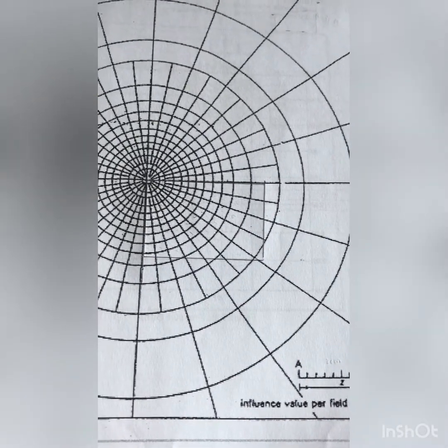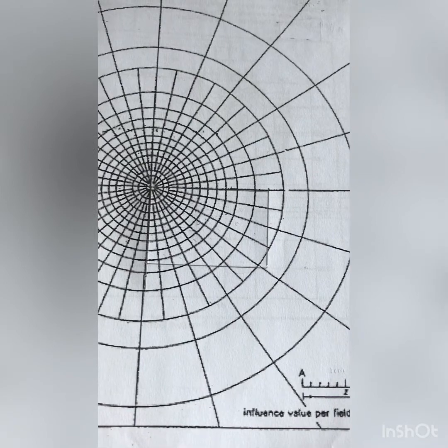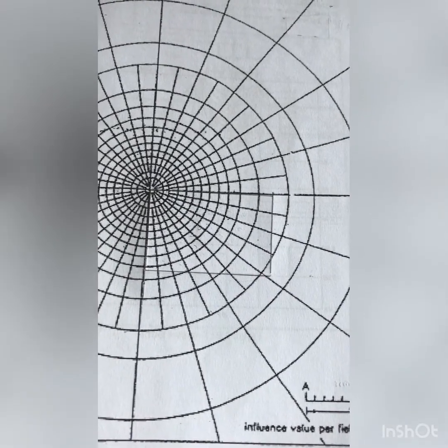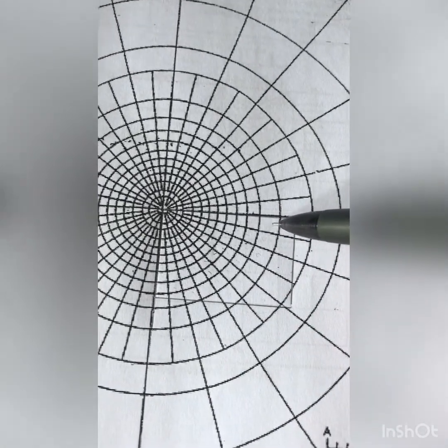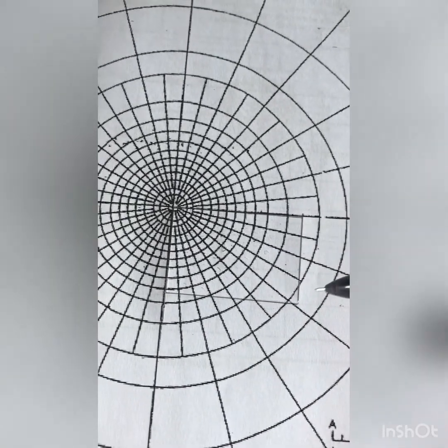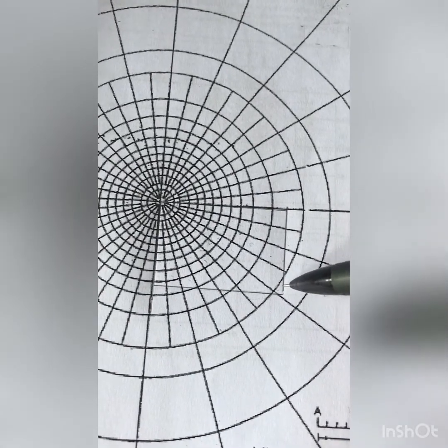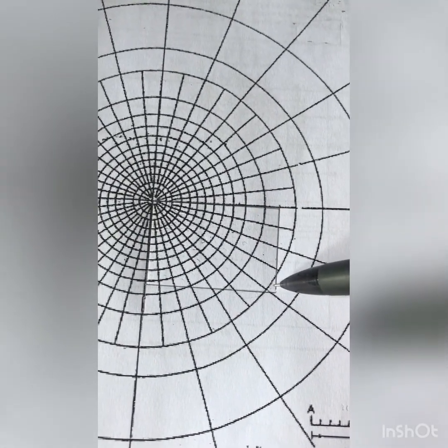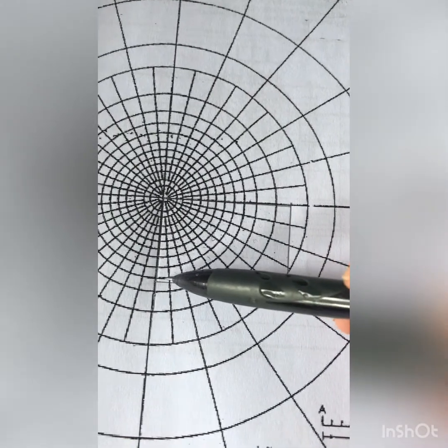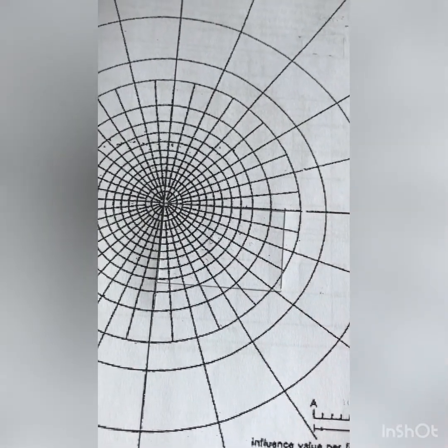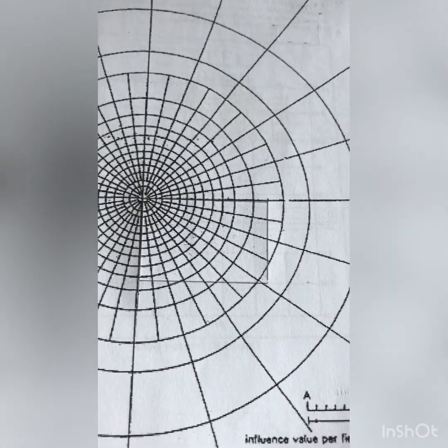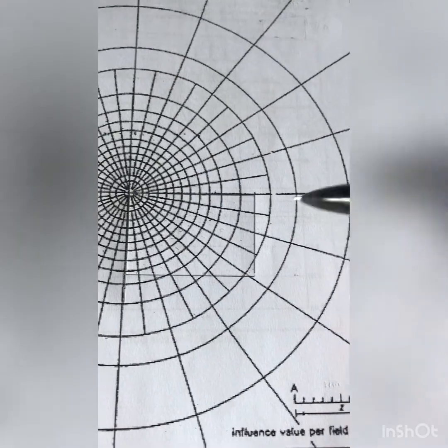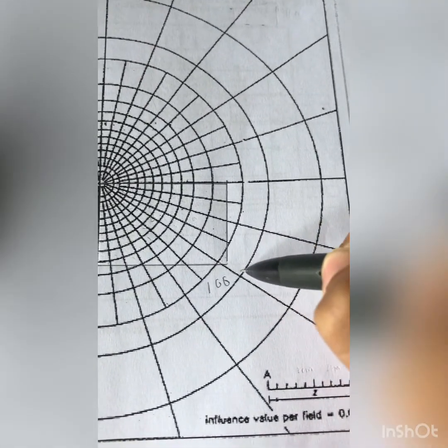So back to the question, it wants us to calculate vertical stress, right? In this foundation B, we count the squares, and when a square is not complete, we count it together with the other partial ones like this, and top up to make it 1. So the total that I get is 100 squares.